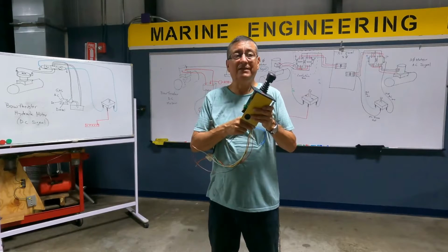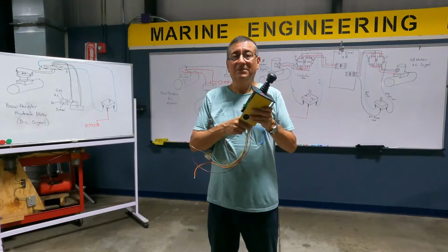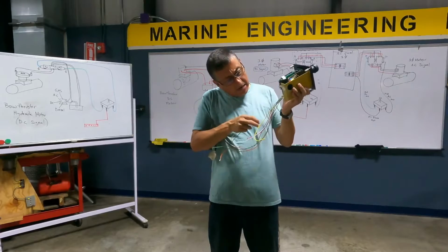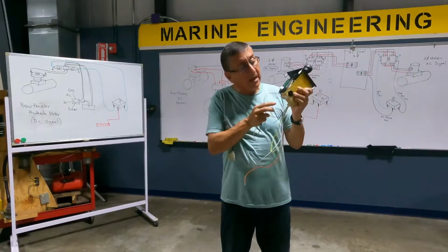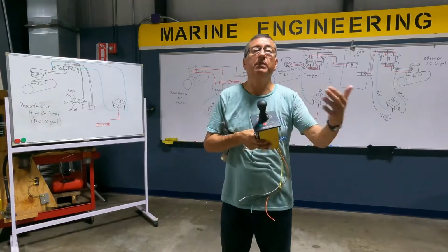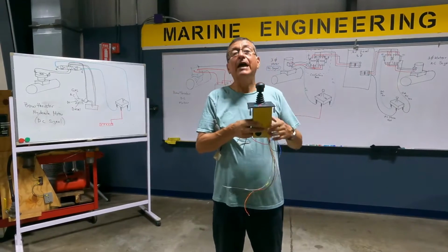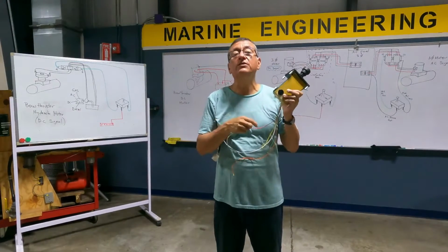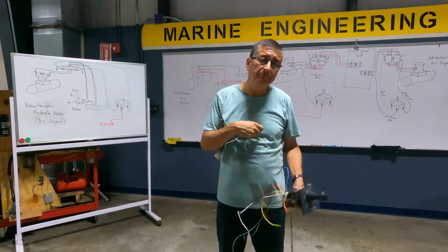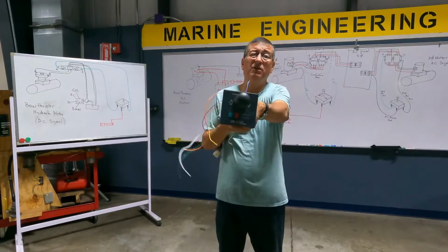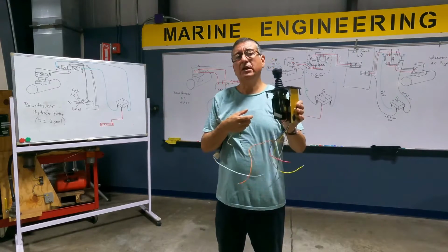That's it. I put power between the red and the black, and I have power here in the display. Now I need to identify which one is the common with continuity. You spend 5 minutes, 10 minutes checking that.